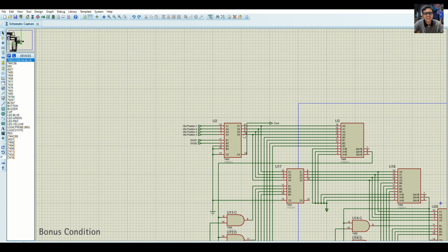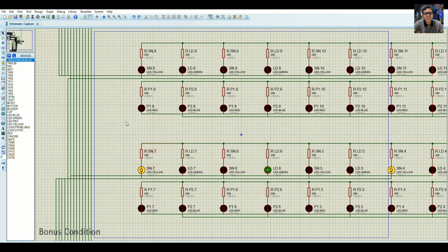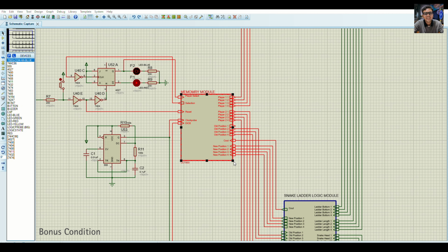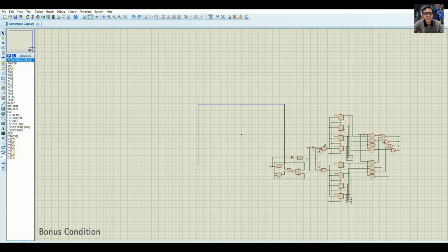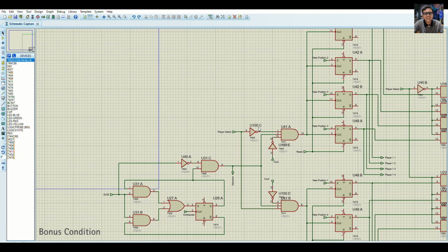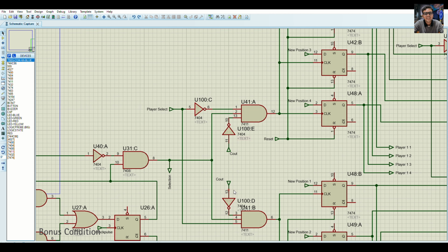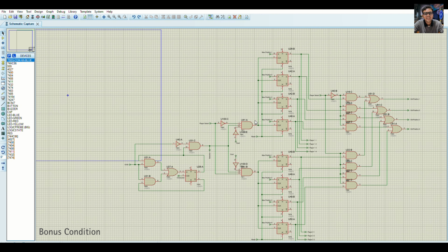Otherwise, in the majority of cases, the carryout will always be 0. So whenever the carryout is 0, which is the majority of the time, we can see that just beside the D flip-flop sets, we have AND gates, and there the carryout is passed through NOT gates as one of the 3 inputs of the AND gates. This is how carryout always gives 1 to the AND gates as it is 0. So therefore the output of the AND gates becomes normal and the D flip-flops can continue their operation.